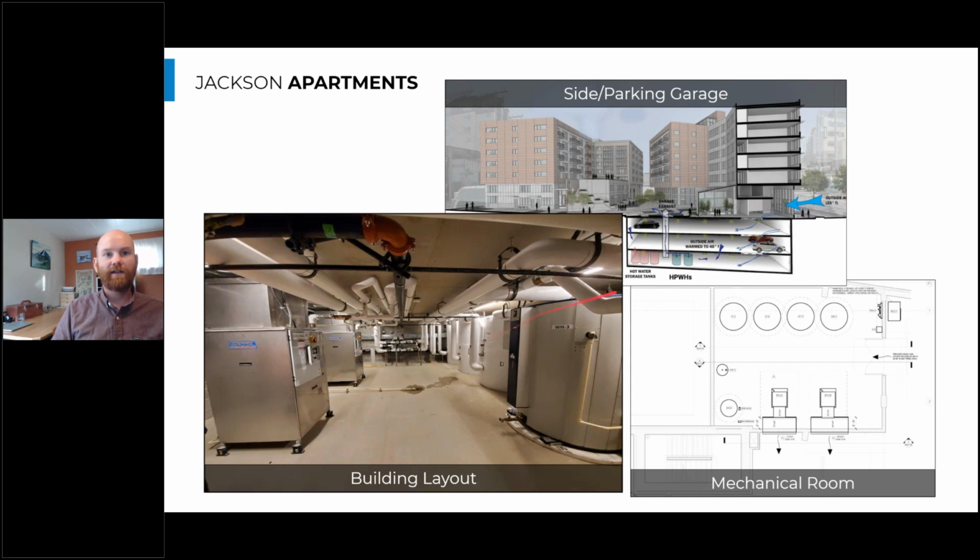So we located these in an underground parking garage that is uninsulated and has a lot of ground contact to provide a buffering effect on that ambient air that comes in. So how this system operates is air is drawn through a ventilated garage door where the cars come in, and that air gets pulled down a few levels towards the heat pump water heating plant.